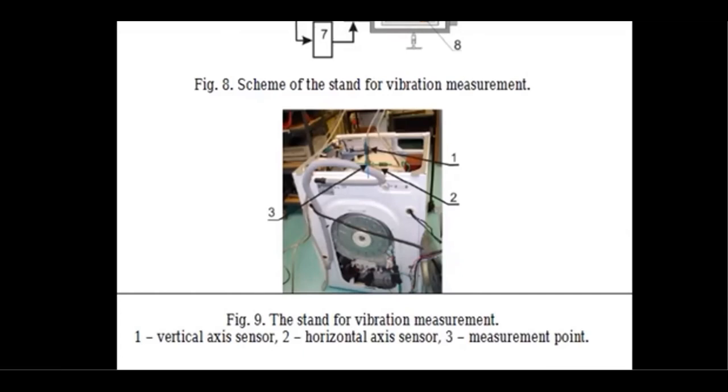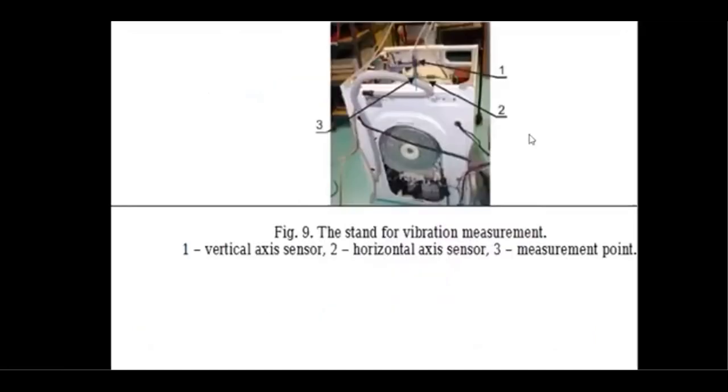So what you see right now, I showed the diagram, basically talks about how we first facilitate to take the vibration measurement of washing machines, so that for a normal washing machine which is running, how are the normal vibrations of those washing machines. And then when the washing machine is under a problem, what kind of vibrations would be there, what kind of AI model we will build to do that detection. Sometimes they call this anomaly detection also.